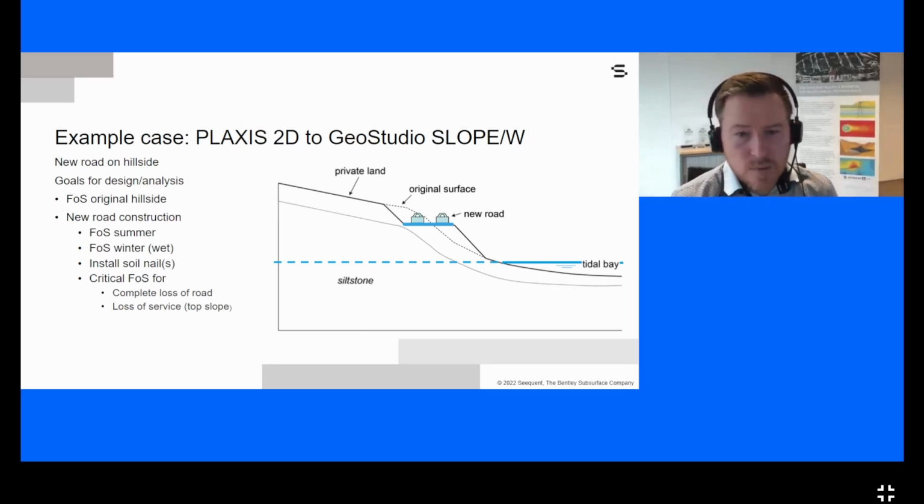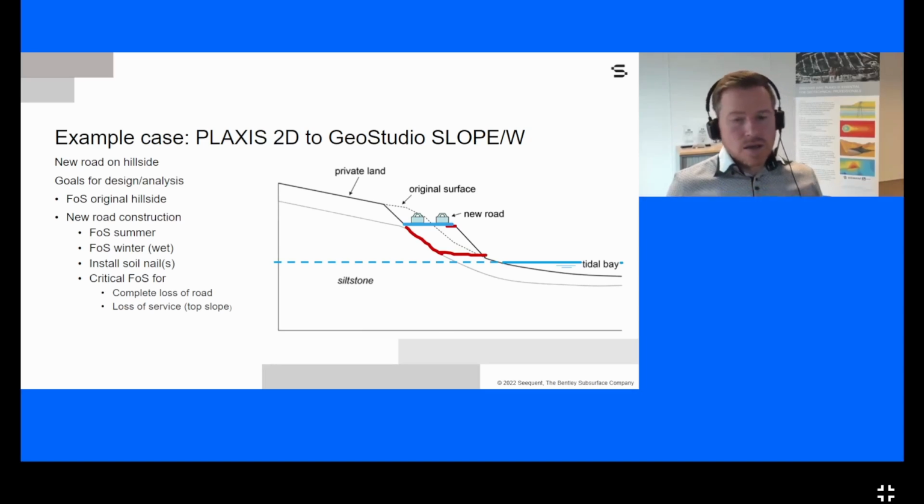We saw that this happened with the limit equilibrium solution, where we had a very localized failure around this area, while the PLAXIS analysis would follow the difference between the weathered siltstone and the intact siltstone, and we just have a slip surface like this. So that's of course something that you have to judge as the geotechnical engineer: would I expect any local failure? And the question would be, say that we have some kind of failure in this. Oh, let me take a different color to highlight this.